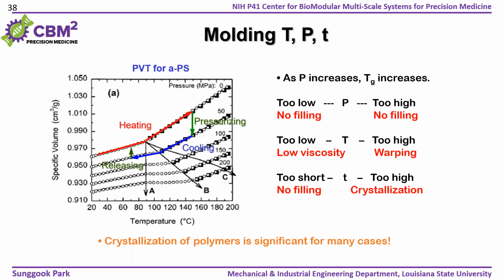Yes. So, Professor Park, what about gases? If you're doing this at atmospheric pressure, with polymers filling the mold with hot embossing, what does all that trapped gas do? Do you evacuate it? I would say for nanoscale molding, the gas trapping is not very important because the amount of gas is not a lot.